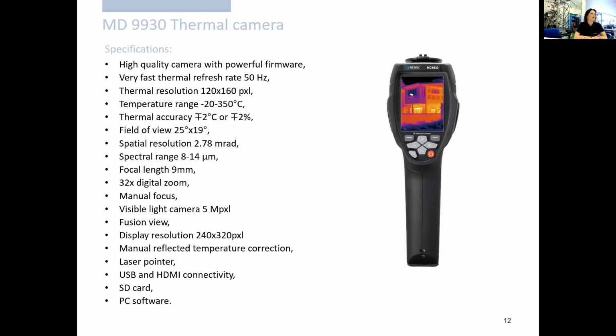I already talked about why this is good, but this is a bit more of a professional feature. There are chances that the users will not set the focus correctly, and the focus is one of the very few parameters of the IR image which cannot be fixed in post-processing. It has to be set correctly already when shooting the image.